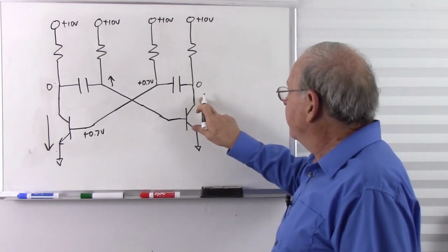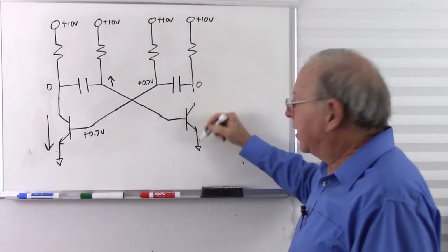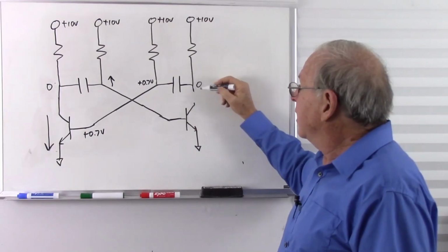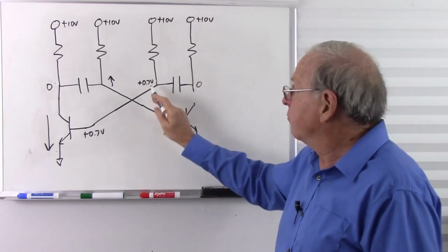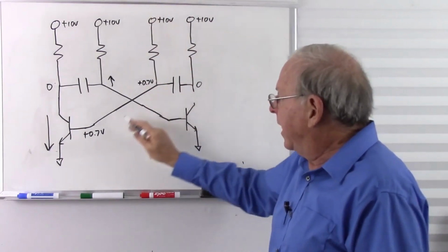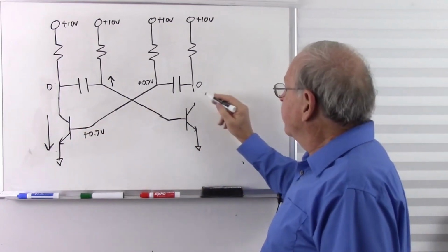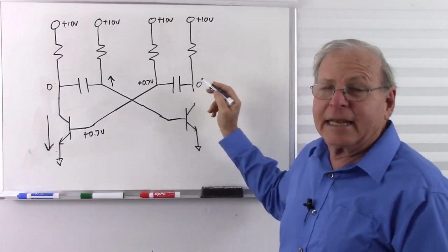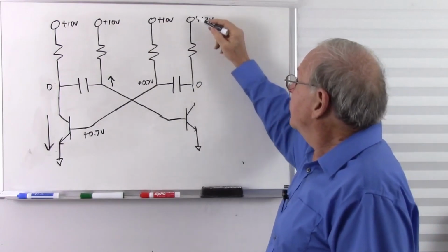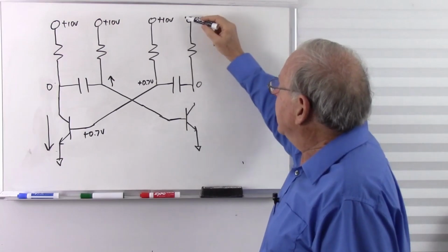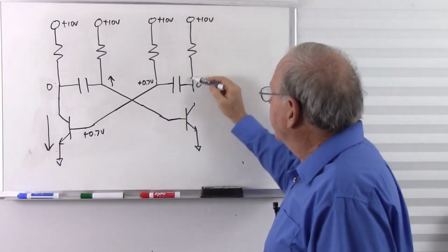And when I turn this off, let's just disconnect it to show that that transistor is off. This voltage really can't rise because that one can't rise either. This would like to jump up in voltage, but it can't because it's being held down by this transistor over here. So that's not really going to go up immediately like it did before. But of course this capacitor is going to be charging, current's going to be flowing in this direction.